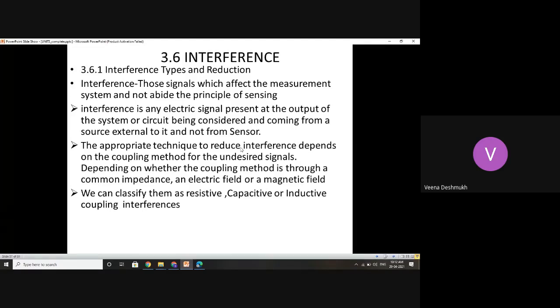So this improved common mode rejection ratio helps in rejecting the common mode signals which originate due to different interferences happening at the sensor end. So the sensing at the sensor end should be so accurate that these interferences should not be transmitted to the next stages. And the measurement should be so accurate that the errors generated here should be suppressed in the instrumentation amplifier stage itself.